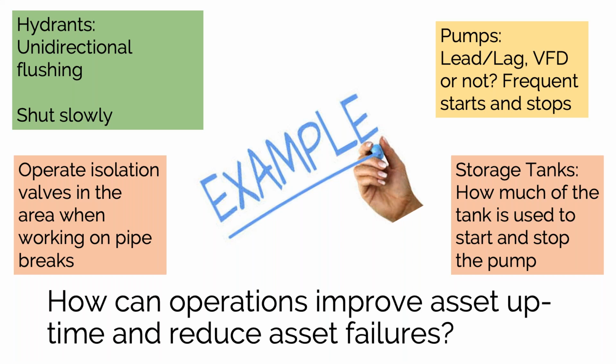We can look at our pumps and maybe look at how we do our lead lag operation, whether we have variable frequency drives or not, whether there are frequent starts and stops, because frequent starts and stops are what really wear out a pump. They're really hard on a pump, so we can address those types of things.